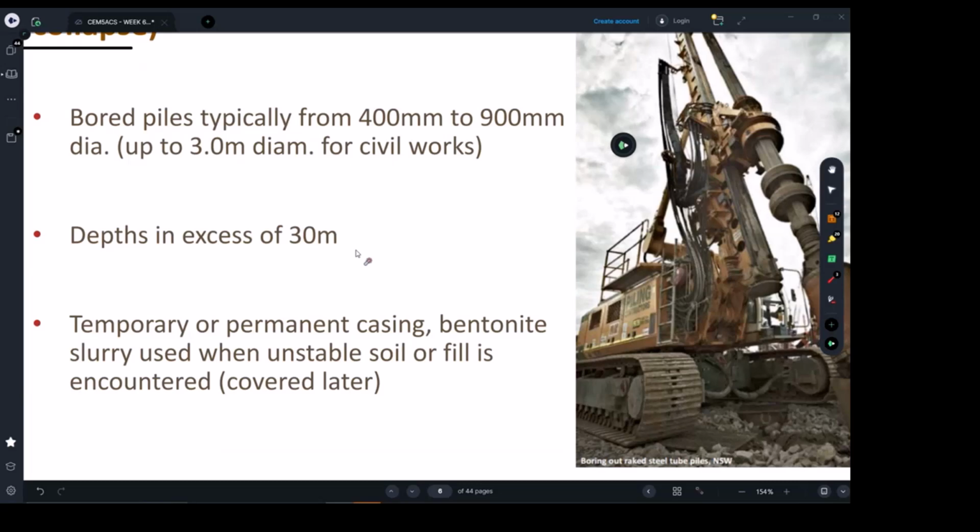If you have trees around the property and the trees seem to be very active, they keep absorbing the moisture from the ground, and that's a problem with trees. They keep taking the moisture and making the soil or the ground not stable, because whenever it has moisture, it's going to dry away, depending on the season, and that will cause movement in the ground.